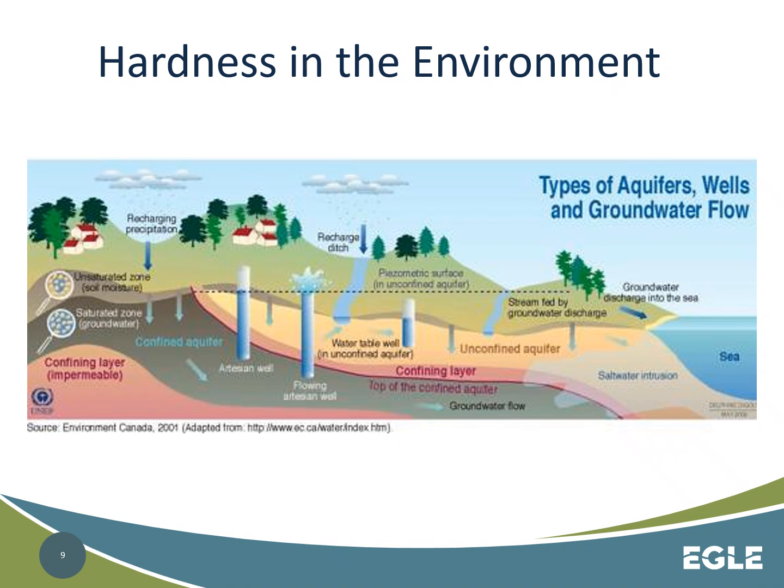If we look at the water cycle, it makes sense that hardness would be higher in groundwater than it is in surface water. In the ground, the movement of water is slowed way down, allowing a lot of contact time with the minerals that are naturally occurring in the ground. In Michigan, we have a lot of limestone and calcium in the ground, which gets easily dissolved into the groundwater, increasing hardness. While surface water is greatly diluted between groundwater recharge as well as other surface waters, runoff, and rainfall, so the hardness is typically lower.